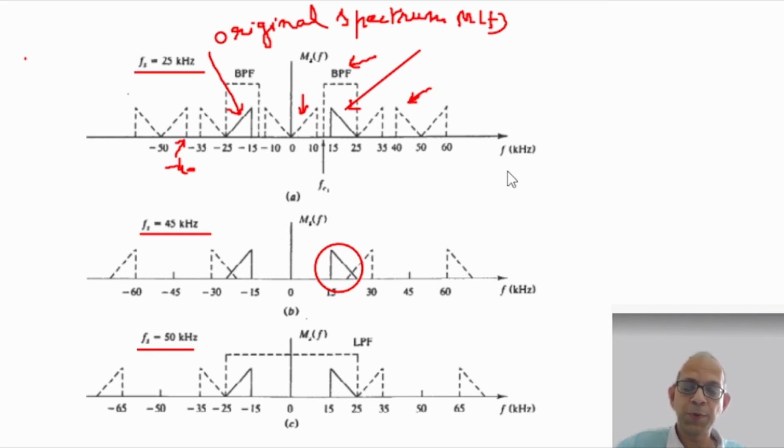So I hope this point will be clear and the difference between the low pass sampling theorem and bandpass sampling theorem is clear. It can be noted that the bandpass sampling theorem works with some specific frequencies only below the Nyquist rate, but if we follow the low pass sampling theorem, that is we are talking about a sampling rate above the Nyquist rate, it will always work whether the signal is a low pass signal or a bandpass signal.